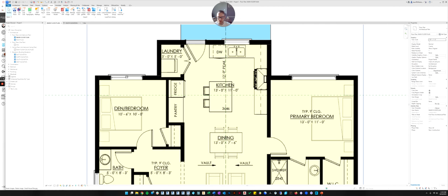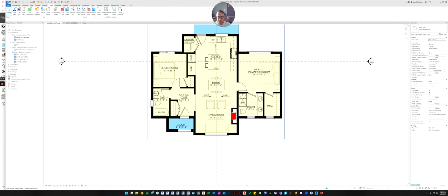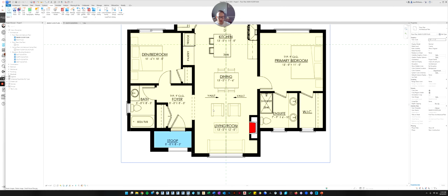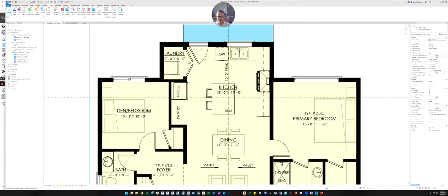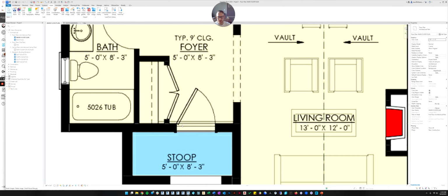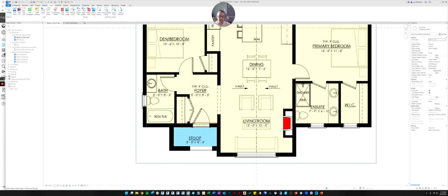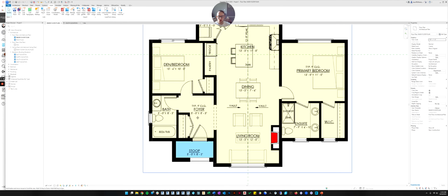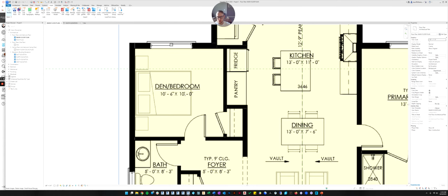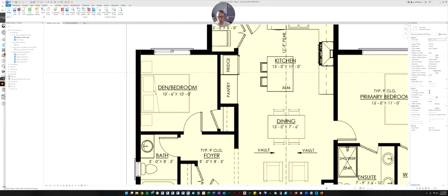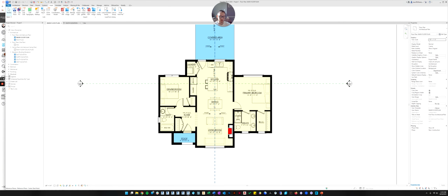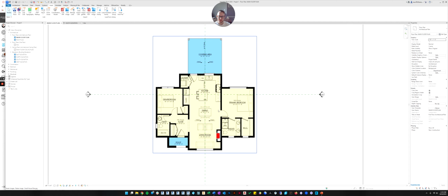So because there's no dimensions on the floor plan, it makes it kind of hard. So there's a couple things we can try. We know typically a front door is 3 feet. That's pretty typical. So we could scale the image using the door, or it gives us the bedroom sizes. So we could try to scale based on one of the dimensions it gives us. I'm going to use the front door, and then we'll test it to see if that's correct,